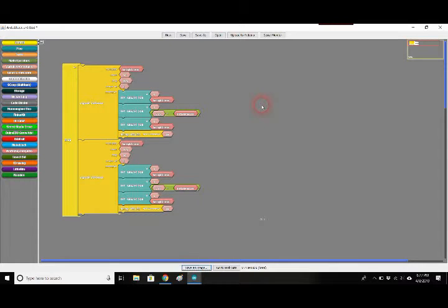What I'm attempting to do here is get one LED to dim as the others brighten, and that same LED to brighten as the other 2 dim. In order to do that, I just want to make sure it's behaving in the opposite way. So when pin 3 sees the number 255, I would like pin 5 to see the number 20. So how do I accomplish that?